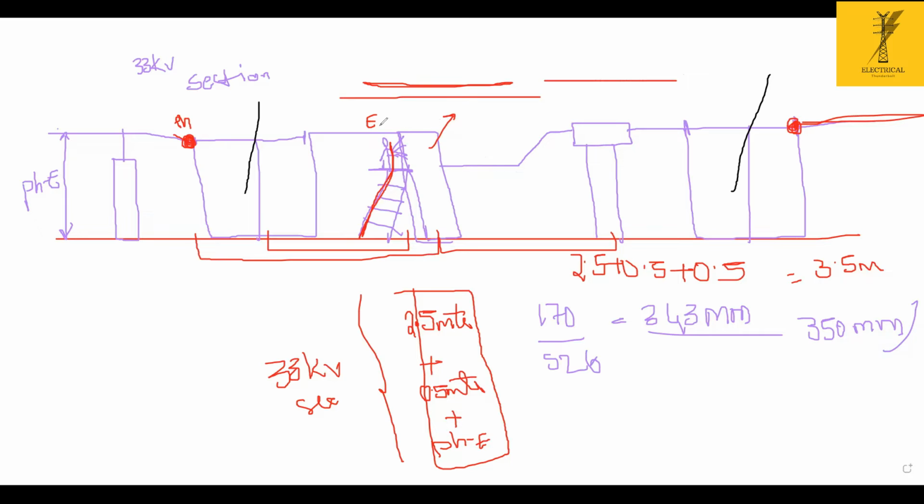But the phase-to-phase clearances, Santosh, we are maintaining only 1.5 meters. Then how? If I am doing any maintenance work on one phase, obviously the total feeder will be off, right? You cannot run the other two phases with one phase in shutdown. So the whole feeder should be shut down if you are attending this.